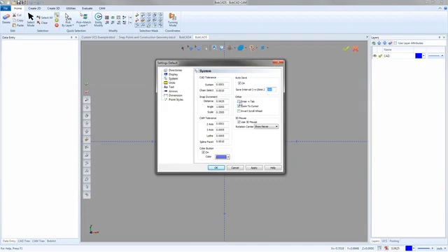So enter equals tab. This is a huge one that I've stood behind people and watched them make this mistake. When you type in values inside of a box in BobCAD or really any Windows system, to get from one box to the next, you normally hit tab. All right. If you want to go back up, just a trick for you guys, if you hold shift and hit tab, it'll bring you back up. So tab goes down, shift tab goes up.